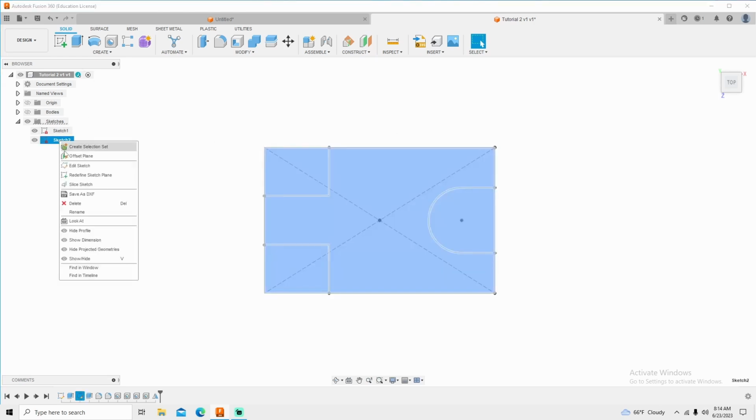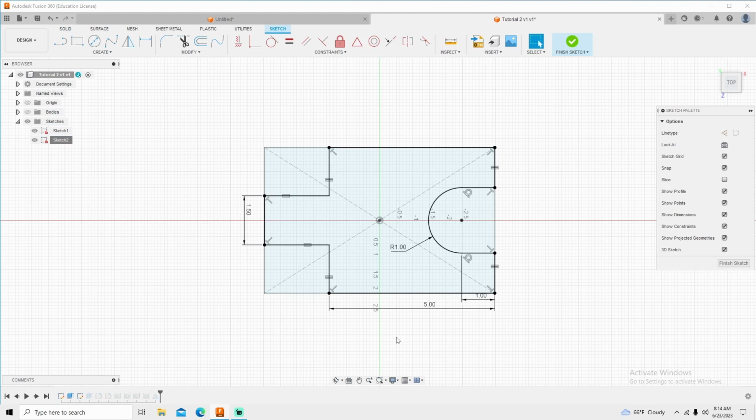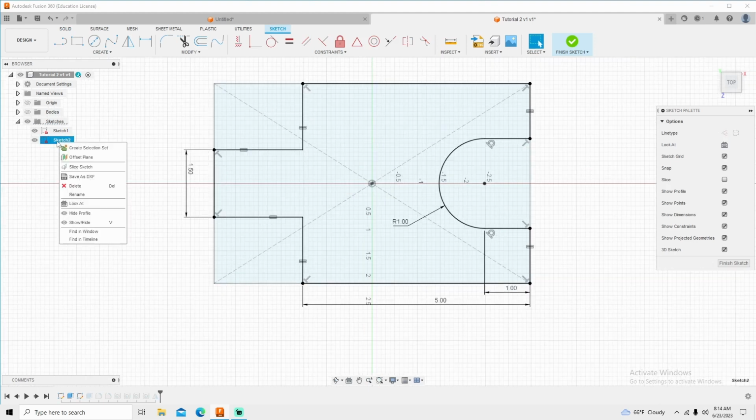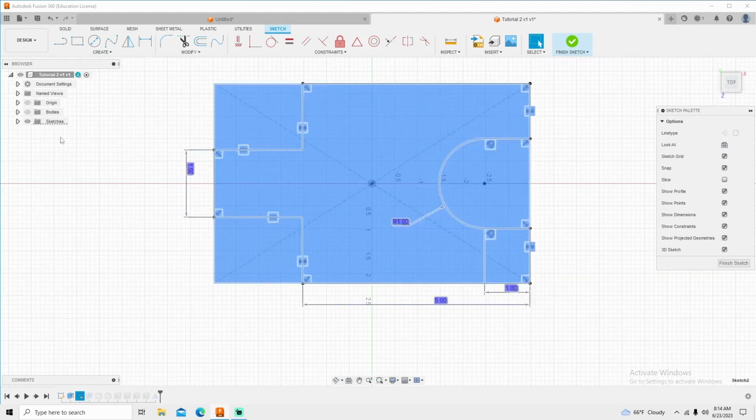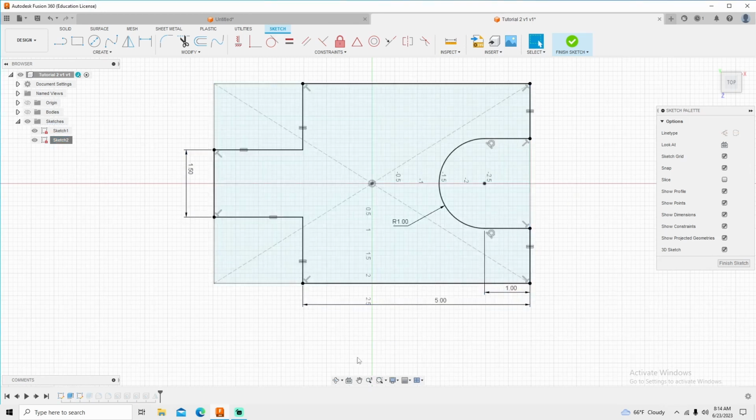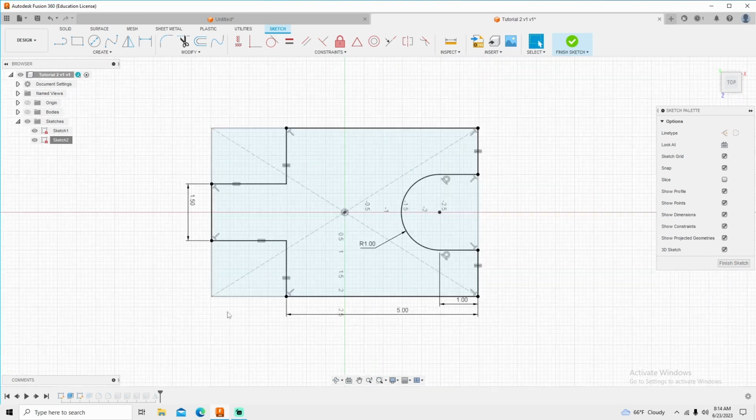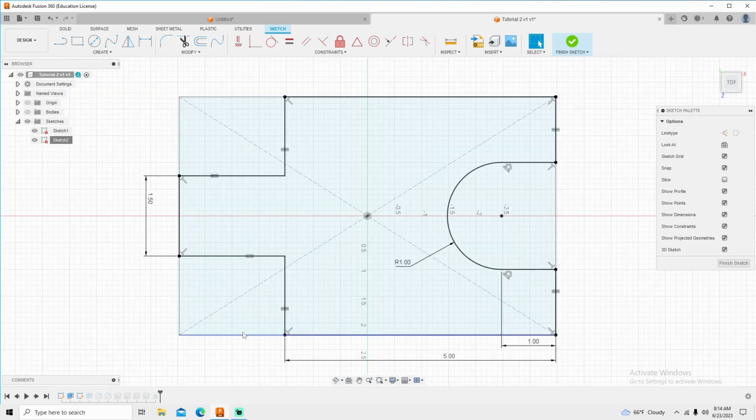If we go back and actually edit this sketch, you can do that by right-clicking on your sketch. First of all, your sketch will probably look like this. You down-click, and then there's sketch 1, sketch 2, right-click, edit, and then you bring this up. But what you're seeing is all the dimensions and all the constraints that Fusion 360 used to bring this part together.